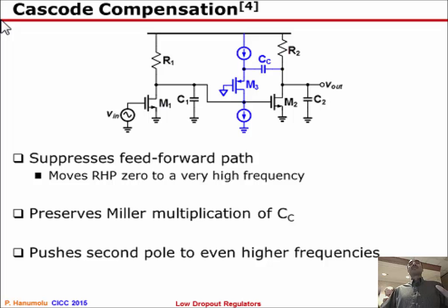One is if the load varies, have infinitely big capacitor to not let the output voltage change. That's one extreme. The other extreme is have infinite bandwidth feedback and regulate the output voltage to not change. Right? So these would be the two extremes.